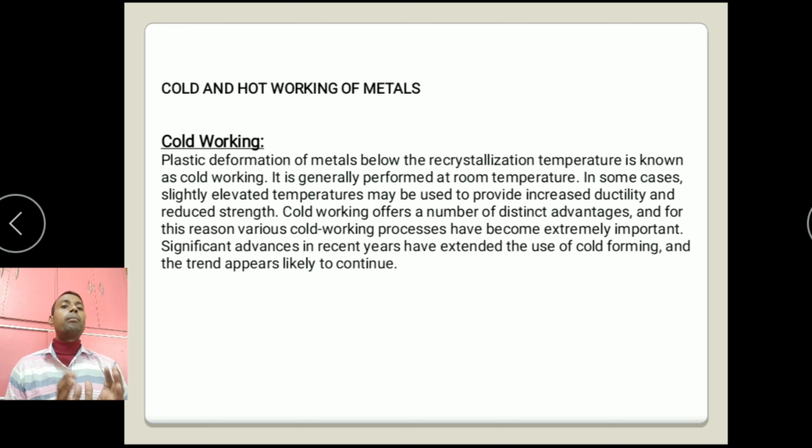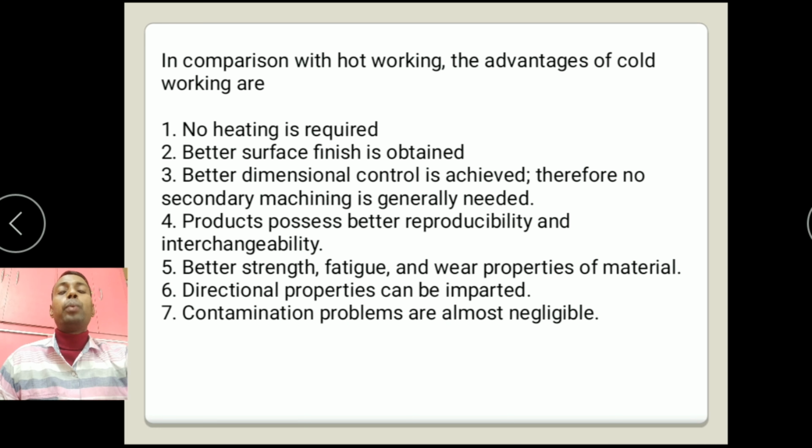Cold working offers a number of distinct advantages, and for this reason various cold working processes have become extremely important. Significant advances in recent years have extended the use of cold forming, and that trend appears likely to continue. What is the advantage of cold working in comparison to hot working? No heat is required, better surface finish, better dimensional control, better reproducibility and interchangeability, better strength, directional property can be imparted, contamination problems are almost negligible.